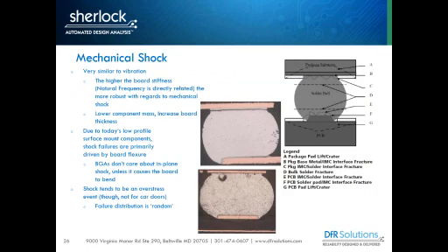When we talk about mechanical shock, it's very similar to vibration. Typically, higher natural frequency is directly related to how stiff the board is. The stiffer the board, the lower the deflection during the shock event. We are also looking at what we call overstress failures. And another thing about shock is that when you shock a board, you typically are yielding the solder joint, causing plasticity.